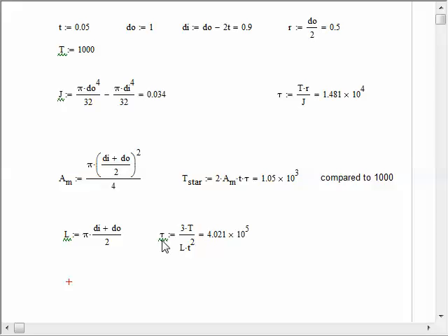And so that illustrates the difference between actually 3 different methods. TR over J works great for circular things, probably the gold standard. The approximation for closed thin wall tubes, right here, and then the approximation for open thin wall tubes to demonstrate how bad an open circular section can be. And that would end this video.